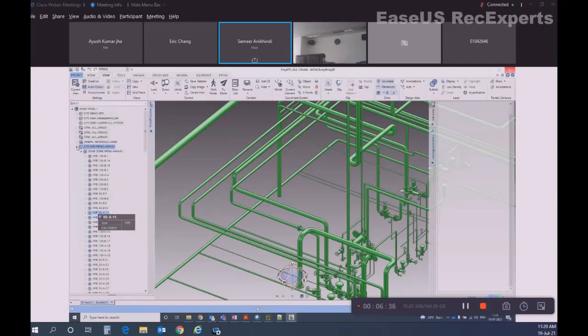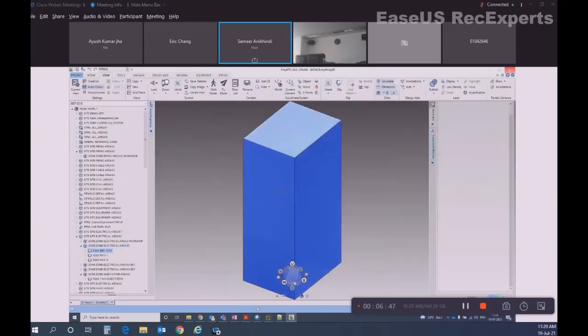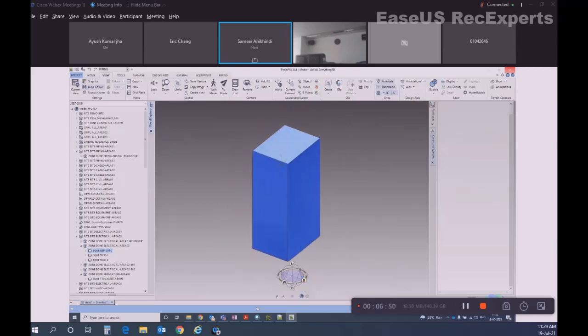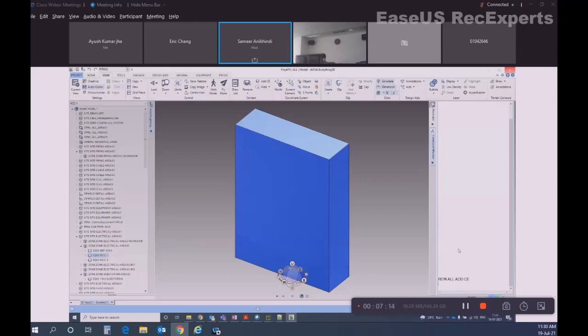For example, I want to go to equipment hierarchy and add just this equipment and remove everything. So this is JBB, this is a junction box. Shift, remove. It will remove everything and just move my focus to this equipment. So shift, drag and drop is to remove everything and add that particular element only. It is very useful. Or you can use a command rem all, remove all, and add c in a single line. Remove everything and add this particular MCC.